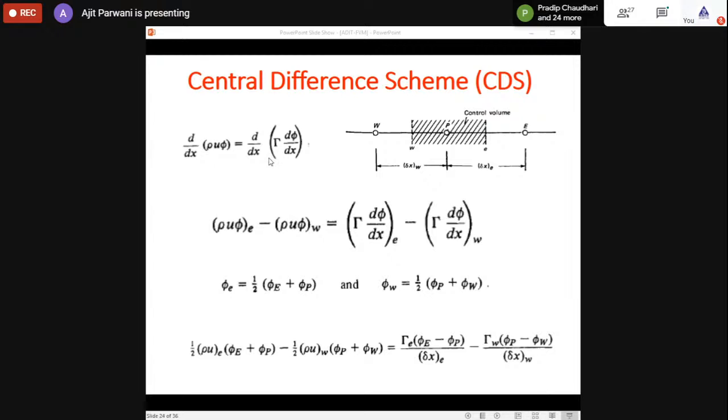If it's a fluid, then our energy equation has one more term, in addition to the conduction term, which has the velocity term. So how do I discretize this equation if I want to solve a fluid flow problem, a convection problem? And what is the difference?